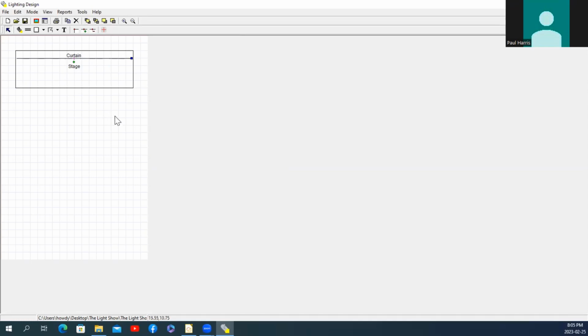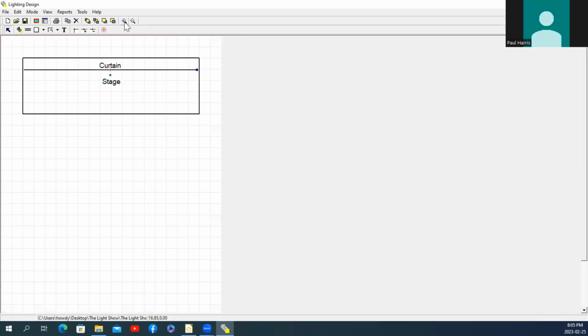The first thing we need is something to hang the light on. In most theaters, there will be a grid of pipes on the ceiling. The convention for naming these is usually to use numbers and letters. Many people like using numbers from side to side, letters from front to back. Up in the ceiling, there'll usually be a place to plug the fixtures in after you hang them on the grid. Each plug will have a unique number on it to tell you what dimmer is connected to the back room. This is important information, as you'll need that information to figure out which light is being connected to where